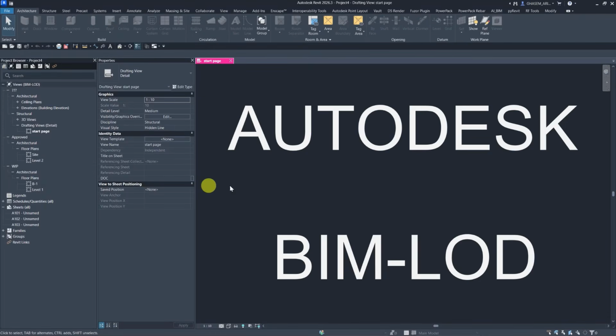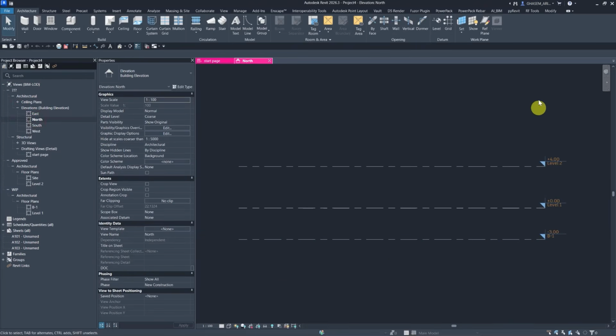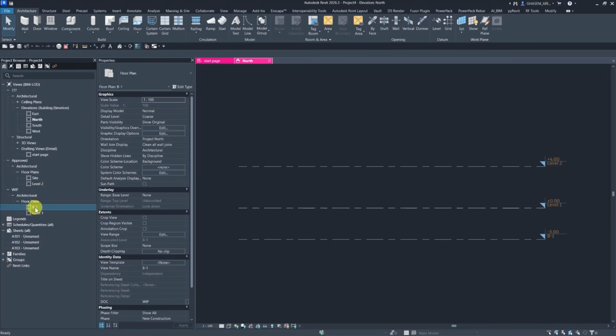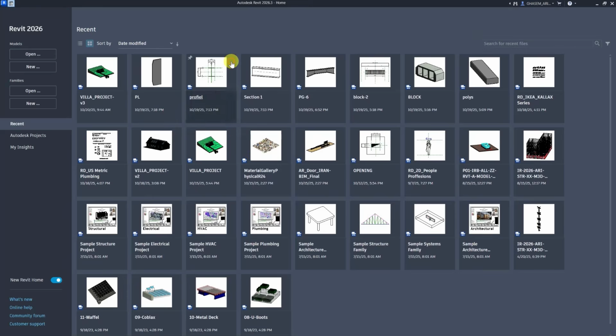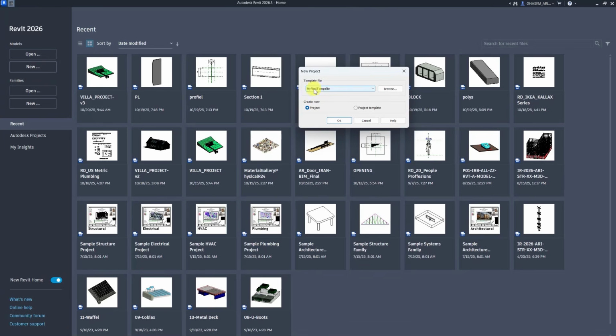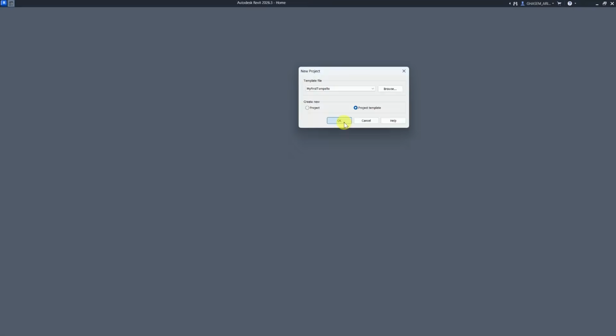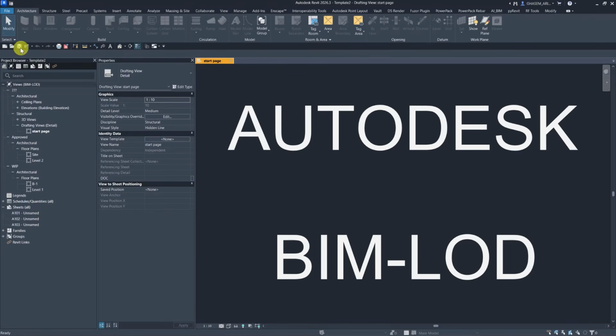And to put this simply, guys, now we have access to all the settings that we just specified together. And now we can, for example, enter one of these views in order to start setting the levels and basically just begin our project. Now remember, guys, completely personalizing or customizing a project template takes time. In other words, you might be developing your templates more and more after finishing different projects. And guys, the steps that you need to take for developing a template is quite the same, or actually even completely the same as creating one. Just add the items and settings that you want, and at the end, save everything.